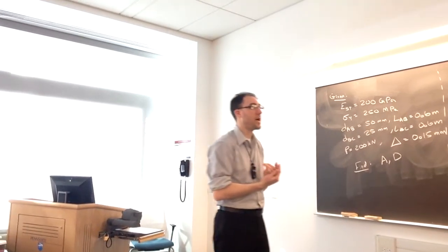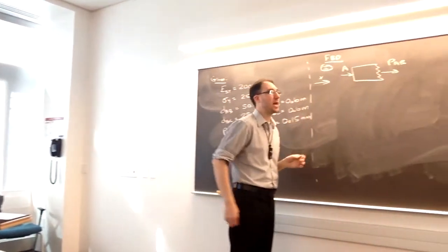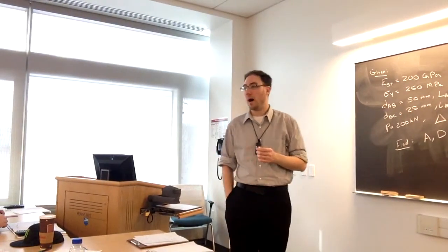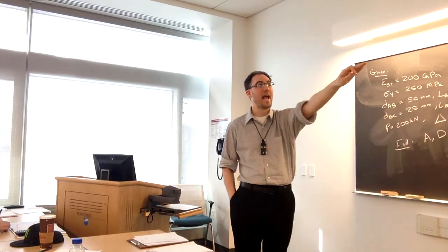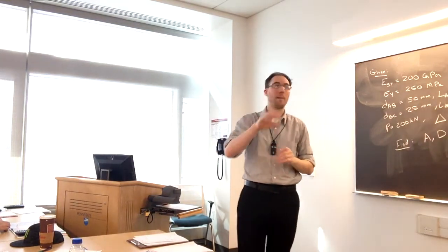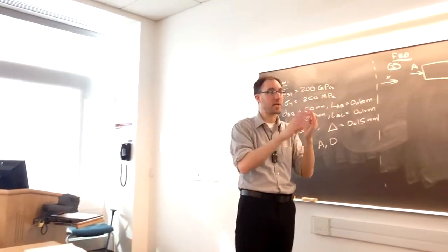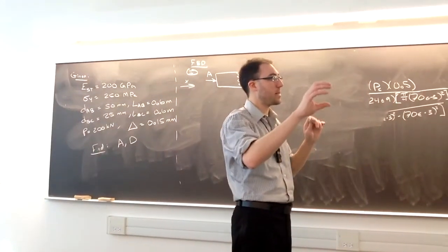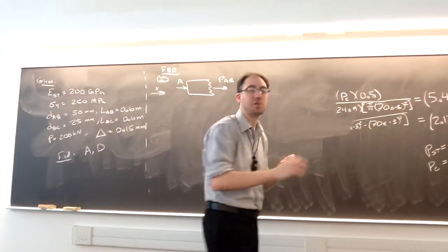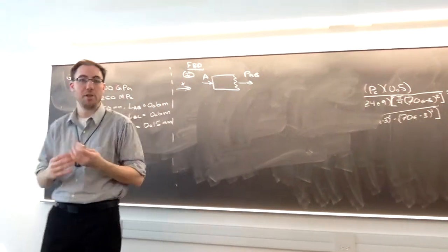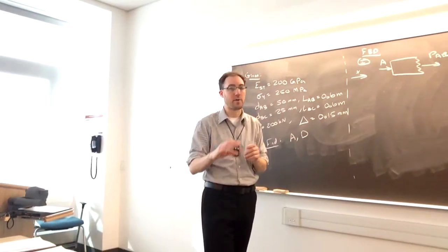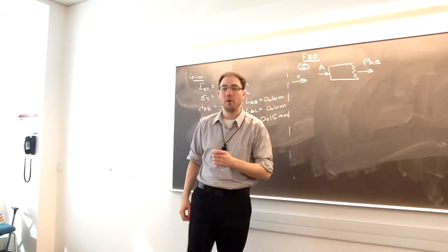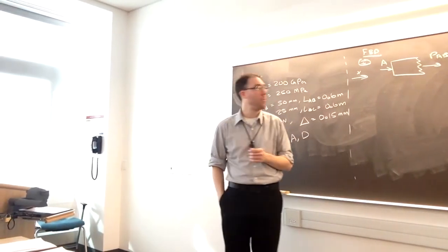When we do that, what do we know about, well, let's start at A. The force at A, because it's bolted into the wall, can either push or pull on the object at A, because we can't pull it away from the wall and we can't push it into the wall. The wall resists us pushing it and the bolts resist us pulling it. However, at D, we have to think about the constraint there. We can't push it into the wall because at D there's the wall there. But we could, in the absence of all other constraints, pull it away from the wall. So what we know at D is that the wall can only push on it at D, but the wall at A can push or pull.